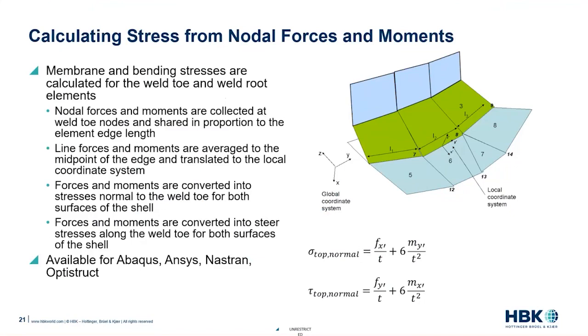It describes both the finite element modeling requirements that are required to represent that particular weld configuration, and how the forces or the stresses are recovered from those nodes in the finite element analysis.